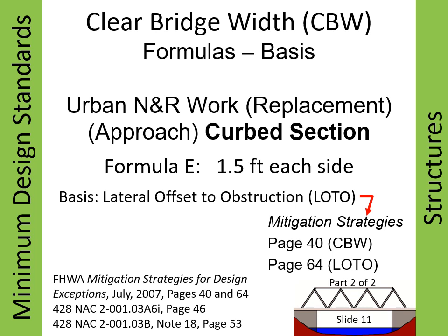Shy distance is an estimated distance average drivers tend to move away from, or shy away from, an object or obstacle. In this case, drivers would tend to shy away from the bridge rail toward the center line or toward the adjacent lane. The state also uses 1.5 feet as the basis for their state highway standards minimum.